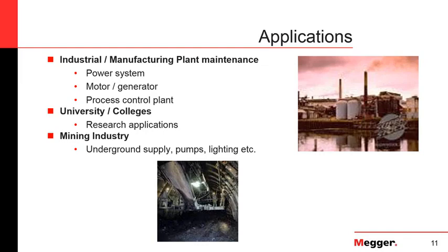In industries that consume vast amounts of electrical power, low resistance testing is a must. Let's say, for example, we have a bus in a substation and it's carrying 12,000 amps of current. If our bus has a resistance of 1 micro-ohm, the power dissipated in that bus will be only 144 watts.